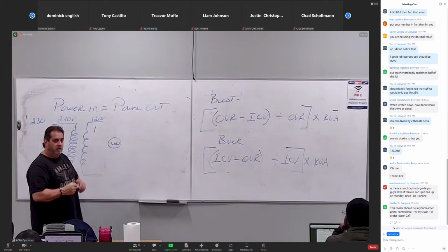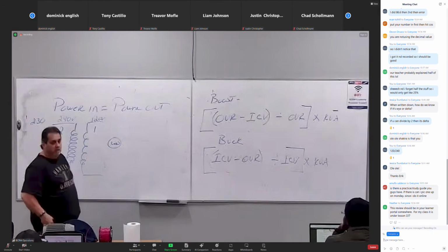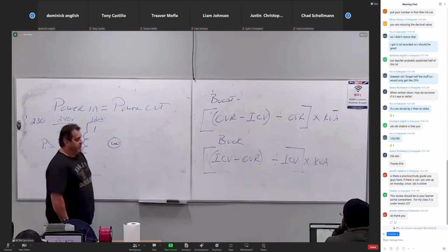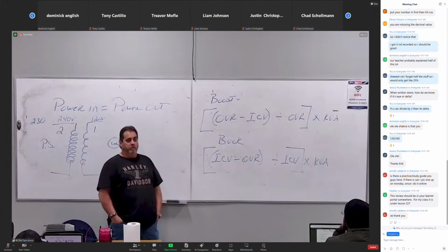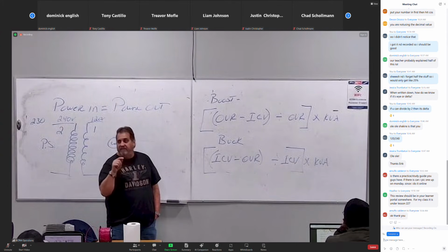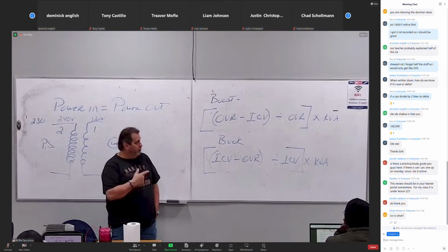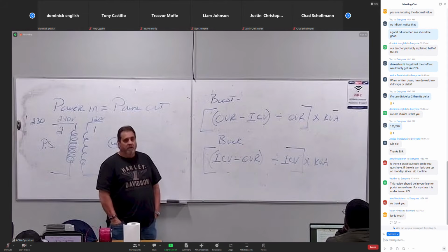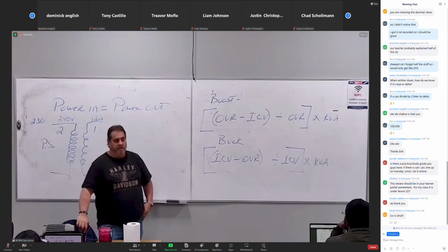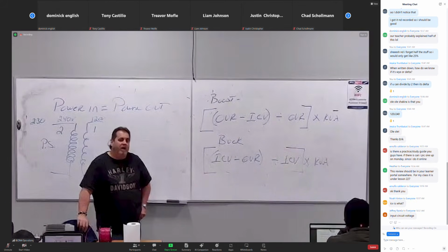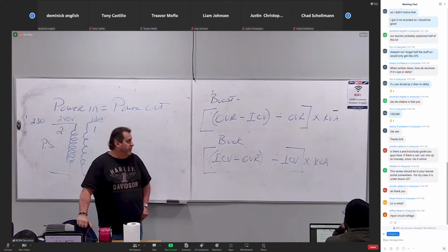Yes. I was just asking, so if the answer is gonna be in KVA, you keep that in KVA? Yes. Yeah, because when you get 0.532, right? That's really a little over a half a KVA. So you might see 0.5 KVA, 0.75 KVA. Yeah, you can change it to watts if you want, but then your answer's in watts. Does that make sense? Yeah, it just makes extra stuff. It does. So this way, most people freak out, they're like, I don't get 0.78. Well, that's 0.78 KVA. So it's 780 watts. So that's why we keep it in the KVA, because transformers are rated in KVA, they're not rated in watts.